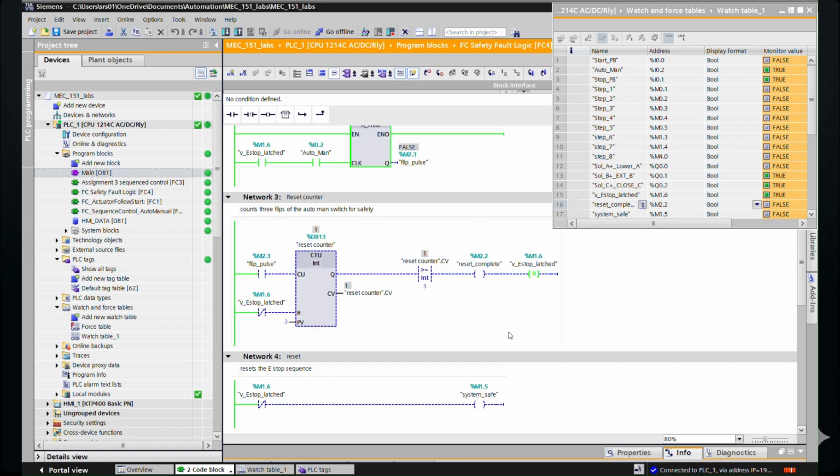Once an emergency stop event is triggered, the PLC enters a strict, non-hazardous software lockout layer. Even when the physical stop button is released, pressing the start button has zero effect on the station, mitigating any risk of accidental restarts while an operator clears components. To recover from this state, our code requires a deliberate manual operator protocol.